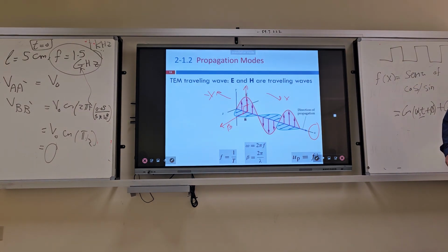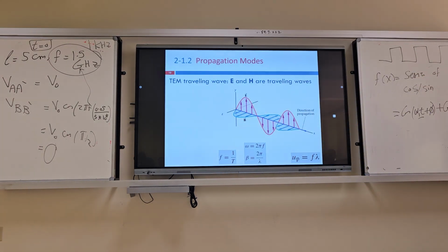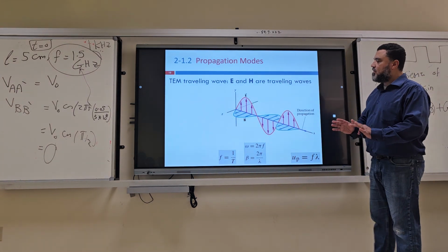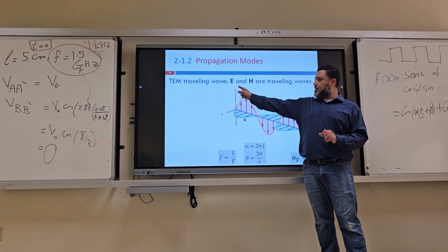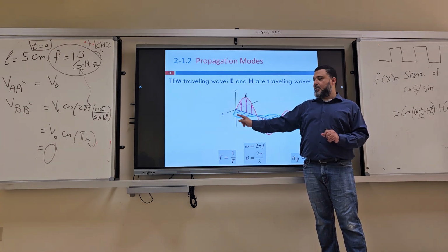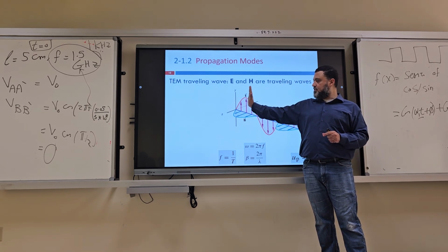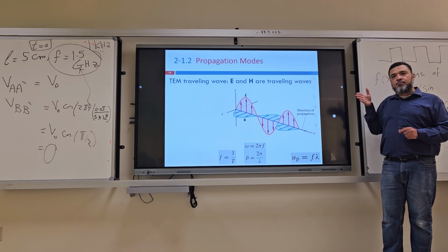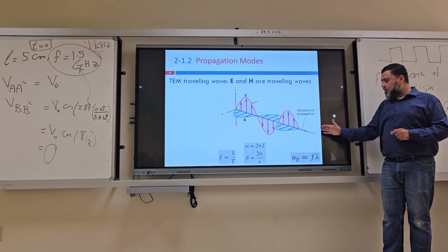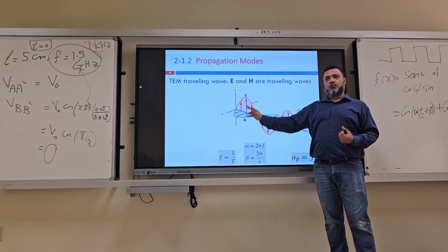Right hand rule. What does this mean? Look at the direction of E. This is how communication takes place. The signal you are receiving has some component E in the Y direction, another component in Z, and both of them, like a plane wave, E and H exist in one plane. And this plane is moving in a third normal direction. The propagation should be perpendicular to the plane containing E and H, or E and B.